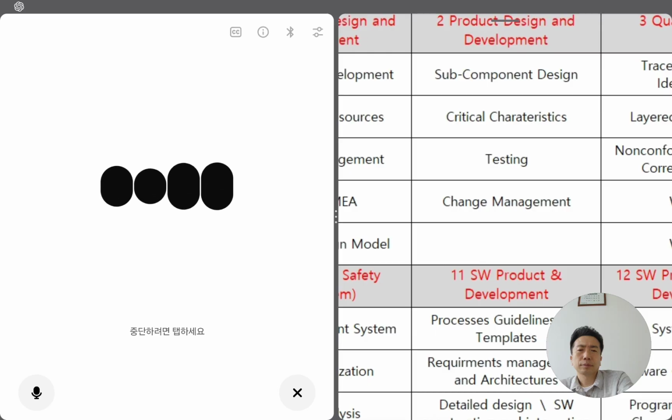In summary, drawings: symbols, CC/SC or trackers. DFMEA, PFMEA: flagged with CC/SC linked to high-risk failure modes. Control plan: marked in table with special control method. Auditor style question based on this.